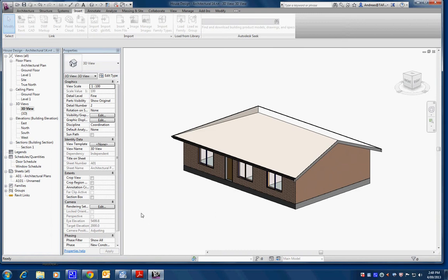If you want to have a 2D, for example, the architectural plan, do the same thing, but double click on the architectural plan, and then you get a 2D floor plan in AutoCAD. Right. Okay, so then we'll do the IFC. You can see that the bottom is actually woken up and it's doing something. All right, finally, now if we had what they call external links in here, Revit links, in other words, if we externally referenced or linked into this drawing another file from another source, like an external reference, or they call it links.